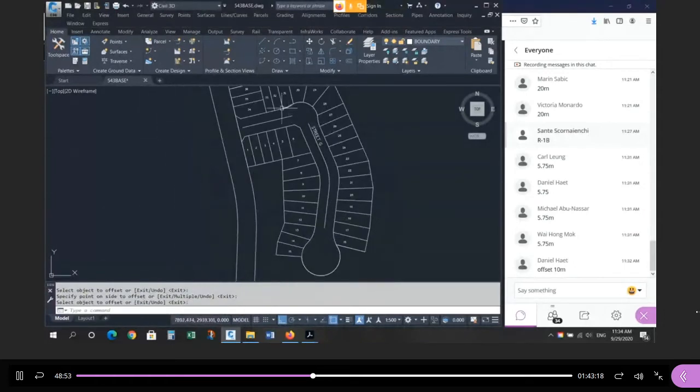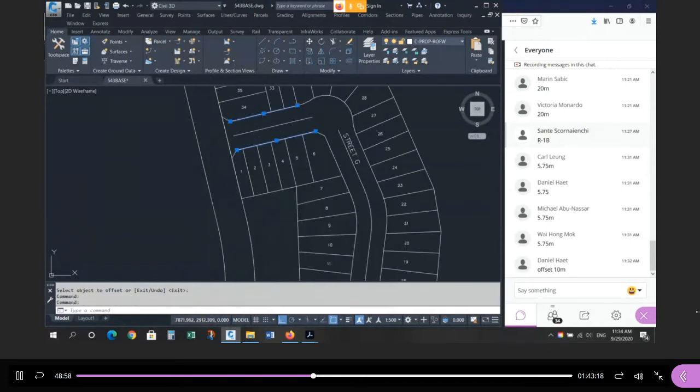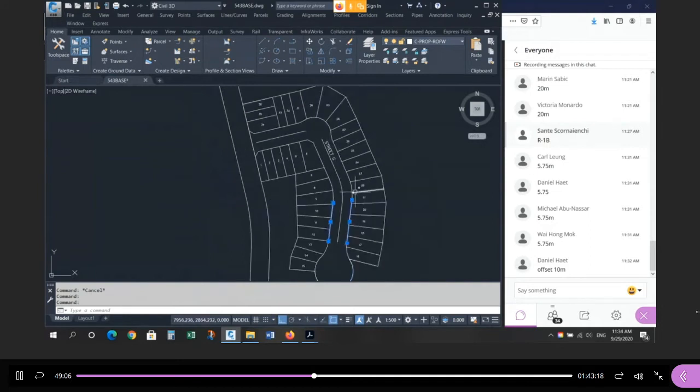Okay, this is unusual. It's not exactly 20 meters wide. This is not exactly 20 meters wide. So where you have a standard width, across from here to here is 20, choose one side. Across from here to here is 20, choose one side. Okay, so you can establish the center line of the road.